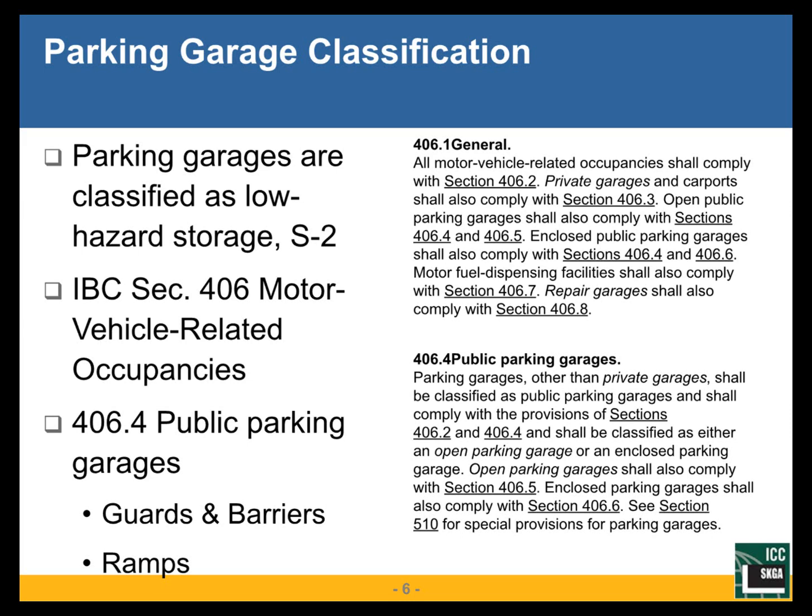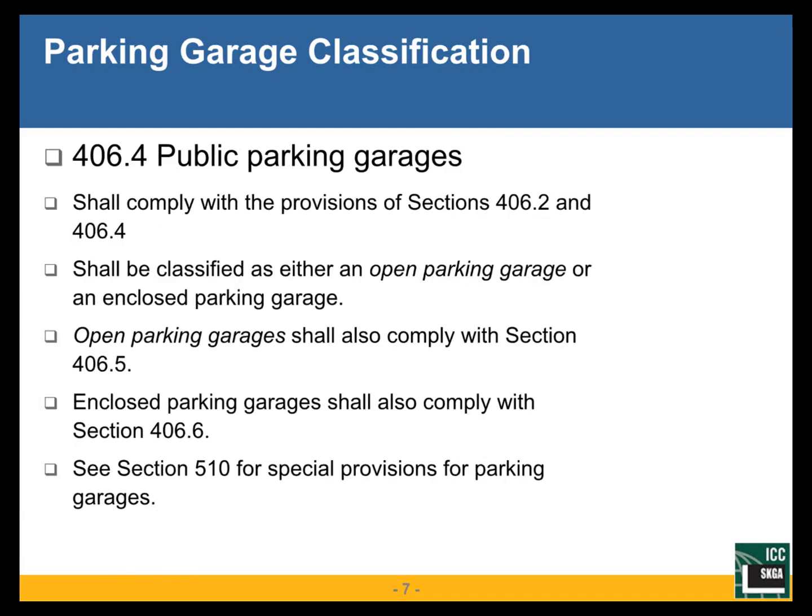There are sections for public parking garages that are covered in Chapter 4, which covers the special considerations of structural types. Public garages must comply with the provisions of Section 406.2 and 406.4.